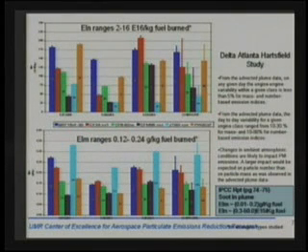They compare pretty comparably to what we saw in the Delta Atlanta Hartsfield study, and interestingly, also compare pretty favorably to what was put into the IPCC Aviation and the Global Atmosphere report back in 1999. They were worried about emissions at altitude, so cruise emissions rather than takeoff or idle emissions. So we're looking at different powers, but even back then, the numbers drawn from some field studies put things on the order of a fraction of a gram per kilogram fuel for the mass, and in the range of several tens times 10 to the 15th particles per kilogram fuel. So we now have a pretty good set of data that span a wide range of conditions that put these numbers in perspective for both mass and number for particles coming from aircraft engines.